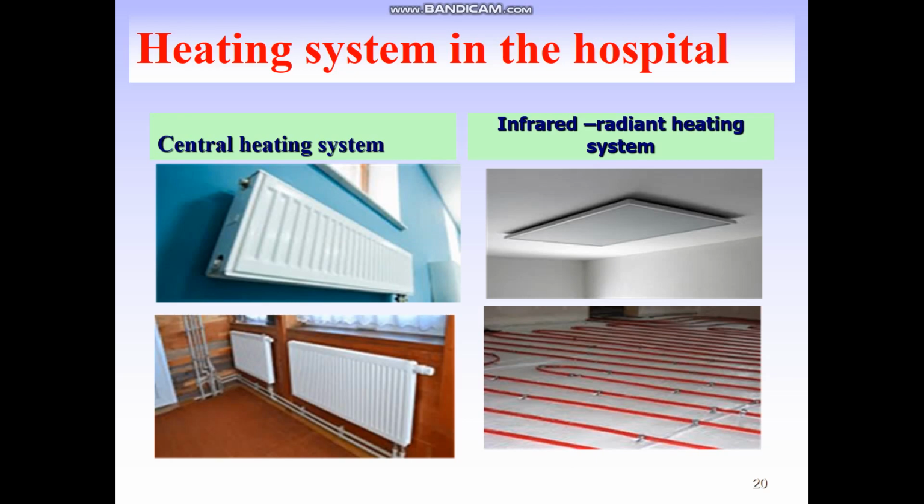In hospitals, central heating is usually provided. The water temperature in the heating device is not over 85 degrees. More hygienic requirements are met by the radiant system, panel heating. Radiant heating is recommended for aseptic premises: operating rooms, maternity, neonatal wards, burns, infection.